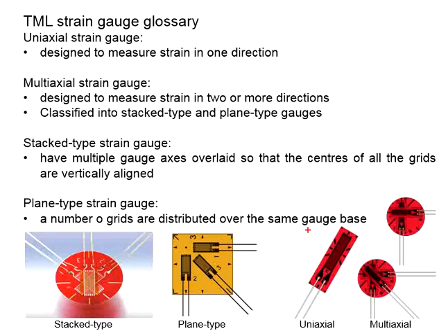You know that the strain gauge is very fragile. If you don't handle it with care, you may damage the strain gauge. Imagine that you need to use this multi-axial strain gauge. You have accidentally detached one of these gauge leads. This will lead to a situation where this strain gauge is not functional. Then you lose the data here.